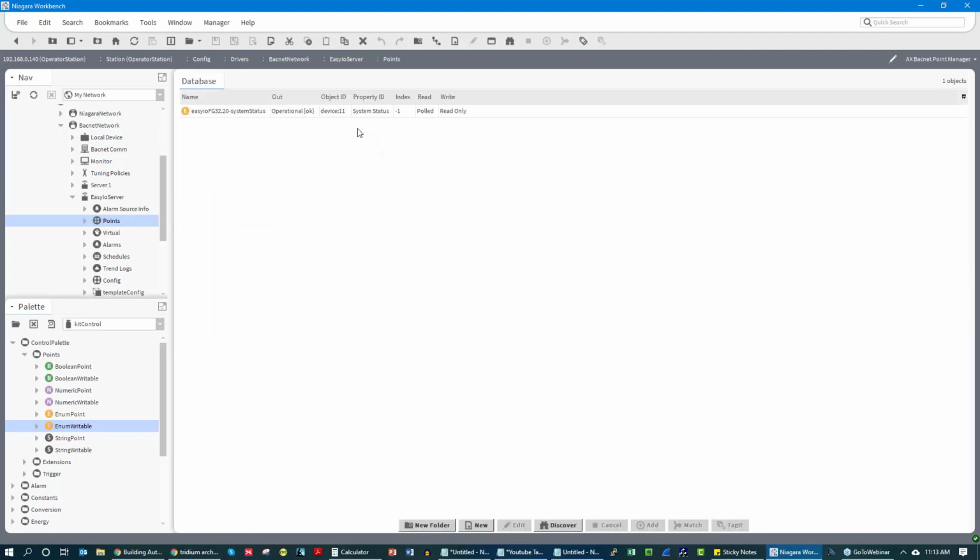Now we can map in what are called logical points and physical points. Logical points exist in the software. That's kind of the benefit of DDC controllers, is that because they have essentially a computer built into them, you're able to have software points, whereas with pneumatics and electromechanical systems, you only had the physical devices themselves. You couldn't add abstract things like set points or resets. Those are things we can now bring into our building automation system in the form of logical points. But we also have physical points. And with physical points, we can see, for example, I have an outdoor air temp.